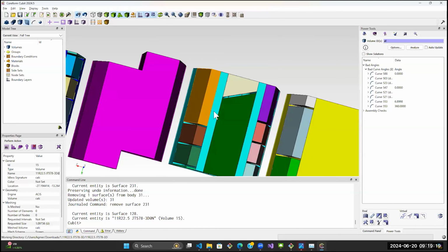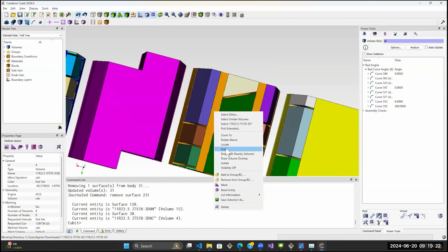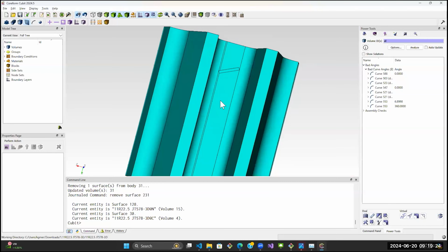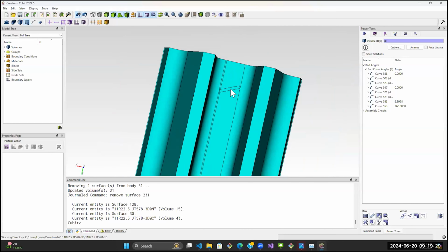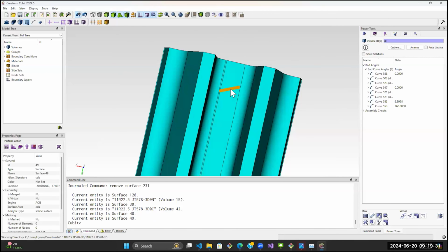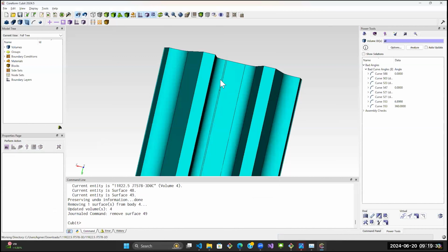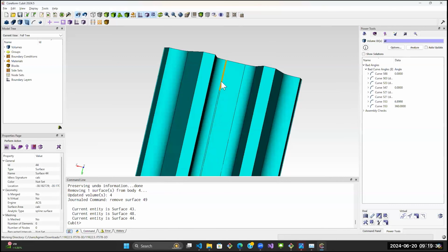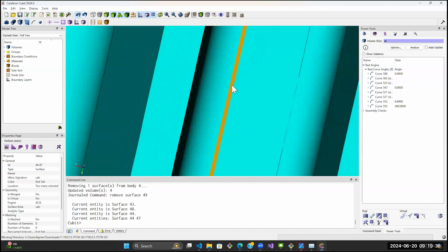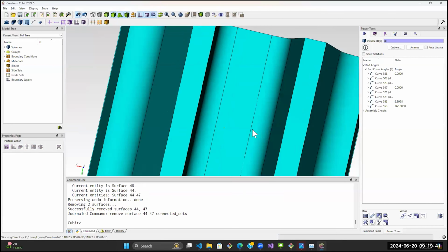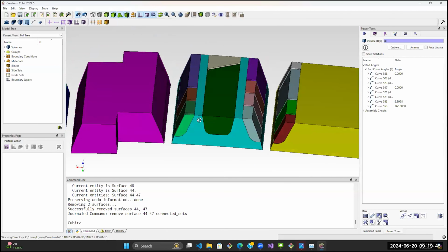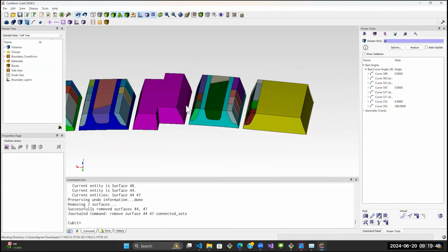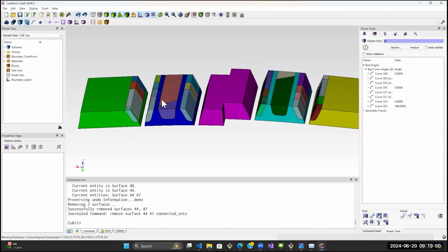Let's look at the volume underneath. Okay, so there were imprints created by the CAD system of those things there as well. So let's go ahead and select that small surface, remove it. We'll get these 2, remove those. And that's cleaned up pretty much on that side. That's great. But we have the exact same things going on the other side here.